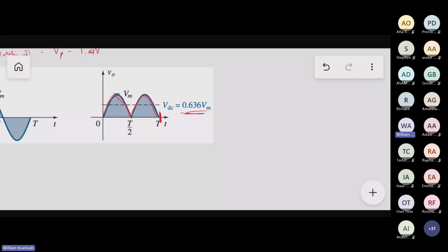Find the peak AC voltage from the transformer secondary. Then the rectified DC voltage after the bridge, then the average DC voltage, then the ripple frequency, and the minimum voltage rating for the smoothing capacitor. So if you're able to design this element, you can actually build it and use it for your PLC and it'll work, because it's still producing the same voltage output. So let's go through it.